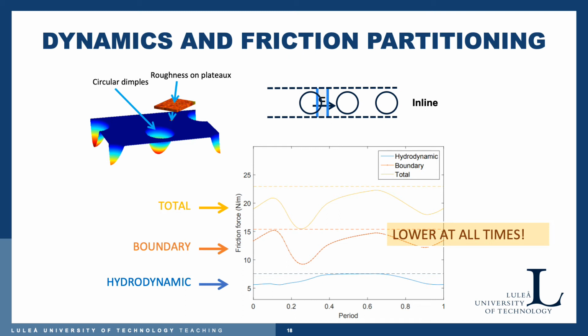But the total friction force will actually be lower than the untextured friction force at all times, and this is because of mixed lubrication. So these dimples relieve the ring from some of the direct contact, and by that it reduces the friction. It may of course increase the wear, but that's another story.